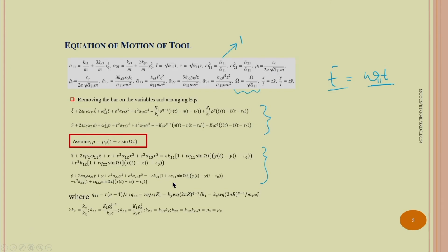Now, as we got the governing equation of motion, you just see this equation is not similar to what we have studied in the case of the Duffing equation, particularly the forcing part on the right hand side. Here the forcing is written in a slightly different way, but the left hand side contains the quadratic and cubic nonlinearity. If the right hand side is equal to 0, we can have a Duffing equation with both quadratic and cubic nonlinearity.